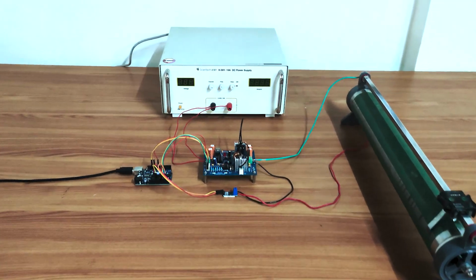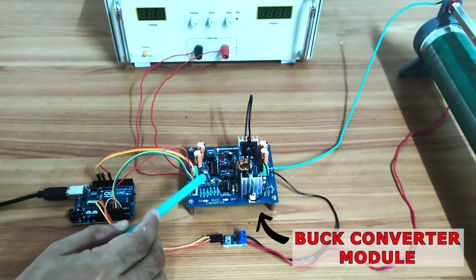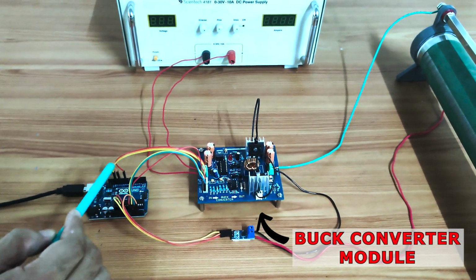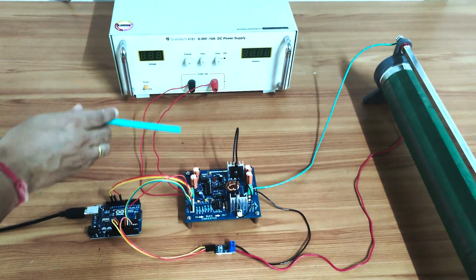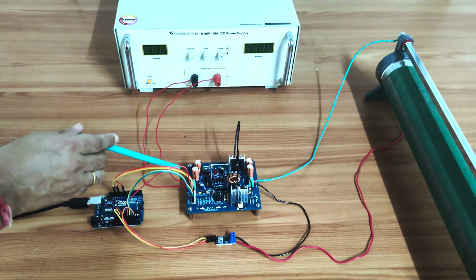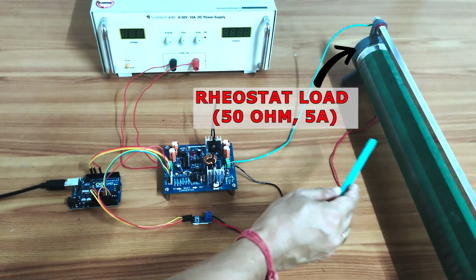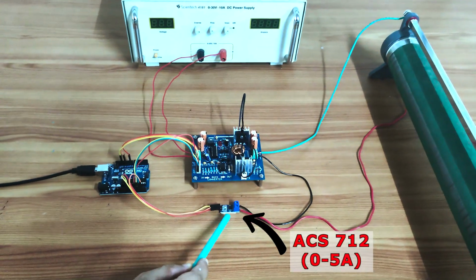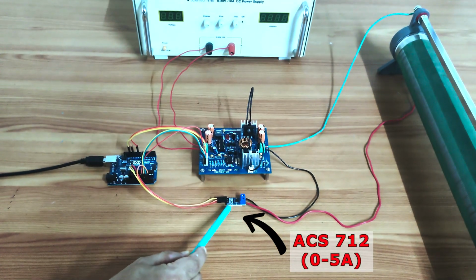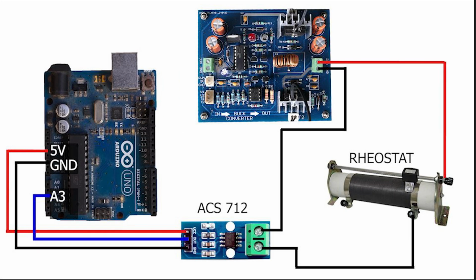Now coming to the experimental setup. Here we have the buck converter which is connected to the Arduino board. Converter is powered from a regulated DC power supply. A rheostat load is connected to the output terminal. The output side current is measured using this ACS 712 current sensor. This is the connection diagram for Arduino and module, and this one is for load and current sensor.